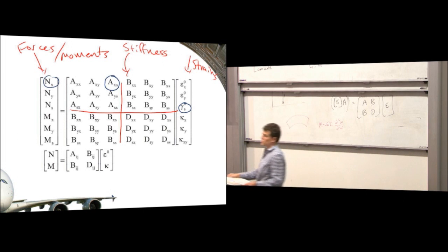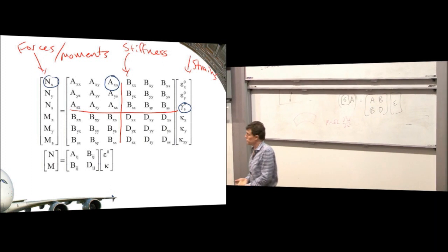So what that means is that I can construct a composite where if I shear it like this, if I try and apply a shear force to it, it'll actually pull my hands in and out in the x direction. Normal materials don't do that. There's no equivalent to this in isotropic materials.